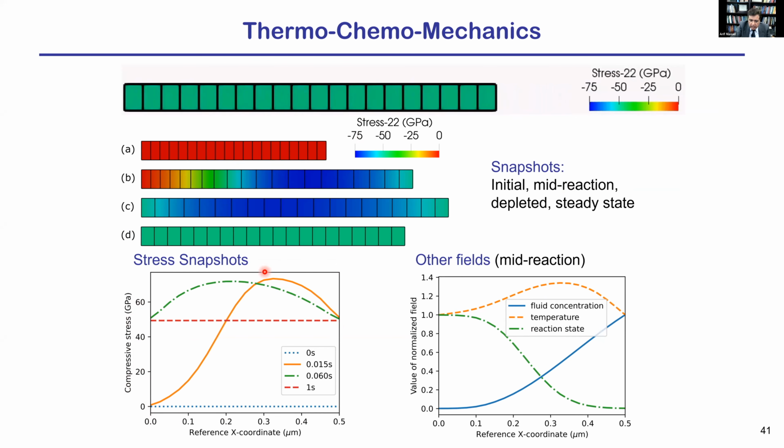So the stress is high in this region, and this portion is not reacted yet. Here, the chemical reaction is taking place all through the domain. Material is completely transformed, but it has not got enough time to dissipate the heat that is generated, and when sufficient time passes, it goes to thermal contraction, and it goes to uniform temperature over the body.